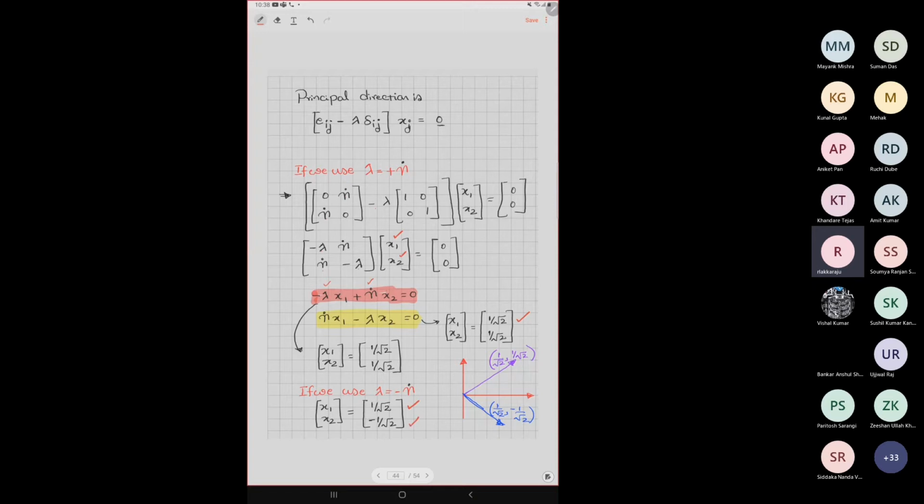That means if I am going to show the direction, x direction is i, y direction is j, and when I look at the velocity, instead of moving either in the i direction or the j direction, if I go along the 1 by root 2, 1 by root 2 direction, or 1 by root 2, minus 1 by root 2, I won't see any shear strain rate, but only an axial strain rate in that particular direction. The shear will always be 0 along those directions.